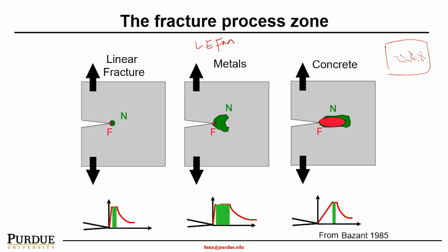So when the concrete is under loading condition, when this crack tip propagates, all those small shrinkage cracks may propagate and merge, and then they become a single large crack. And that becomes a single structure to give the continuity to the already existing crack.